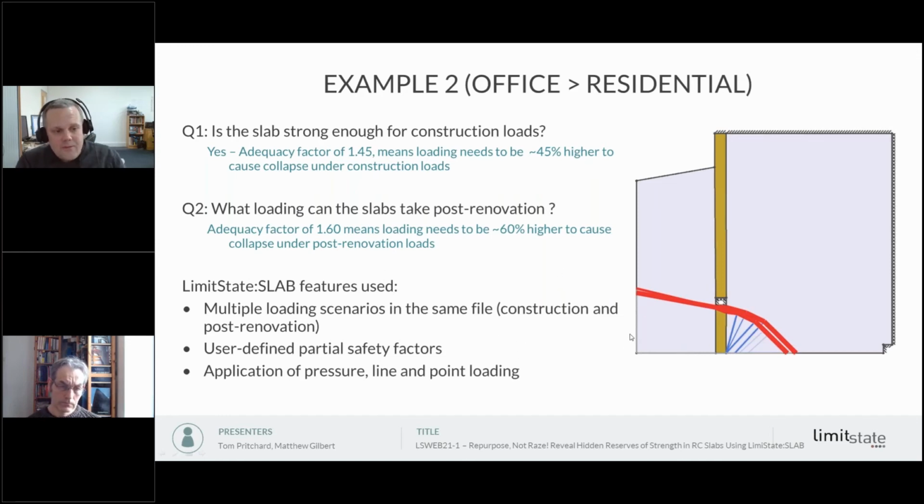And the LimitState Slab features that we used here: we had multiple loading scenarios present in the same file, so the construction and the post renovation. We had user-defined partial safety factors, in this particular case Eurocode ones, and then also we had application of pressure, line and point loading to the problem.